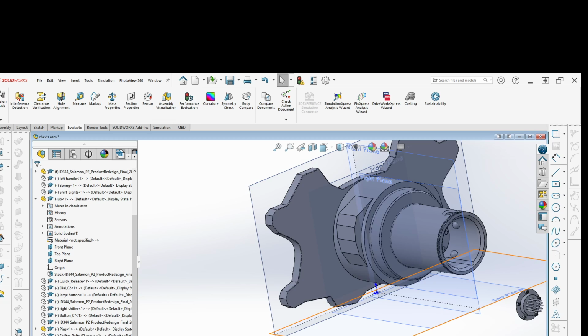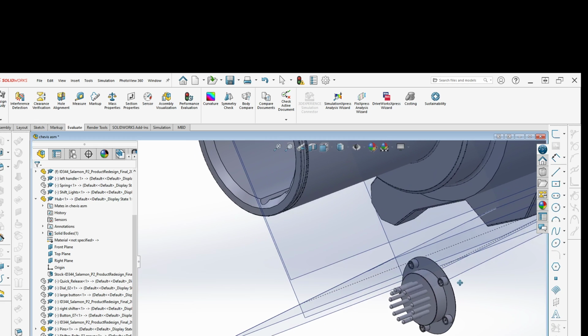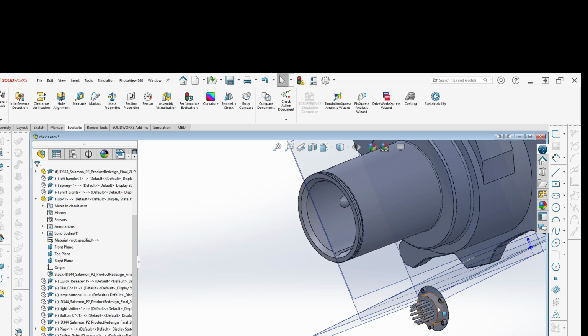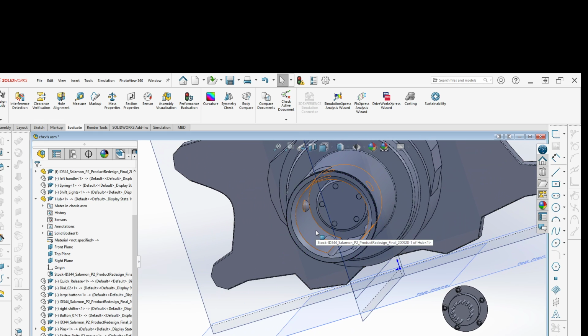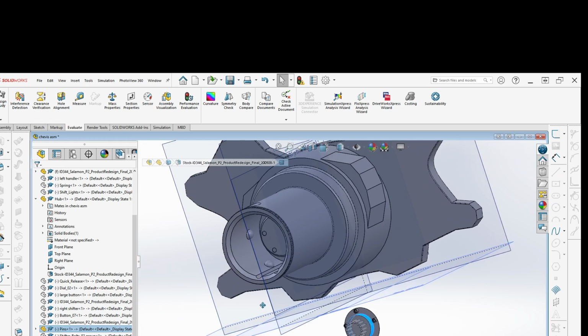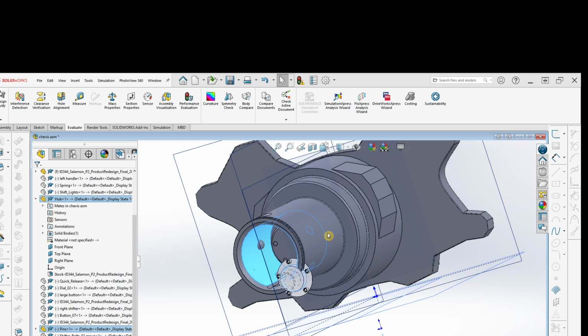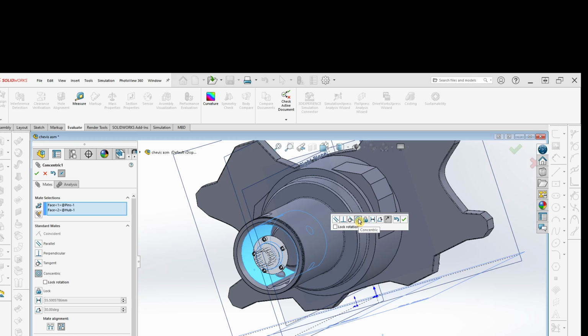There, you're not going to have the same origin for all parts. So you'll have to use these different ways of mating without worrying about the planes. But what I can do is, just like in a sketch, I can say, okay, well, this needs to be dead center of this circle. So I'll take this face and this face, and when I come into mates now, it gives me different options than I had before because they are concentric.